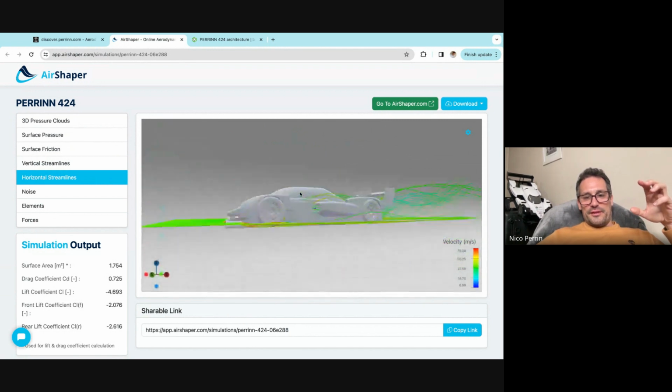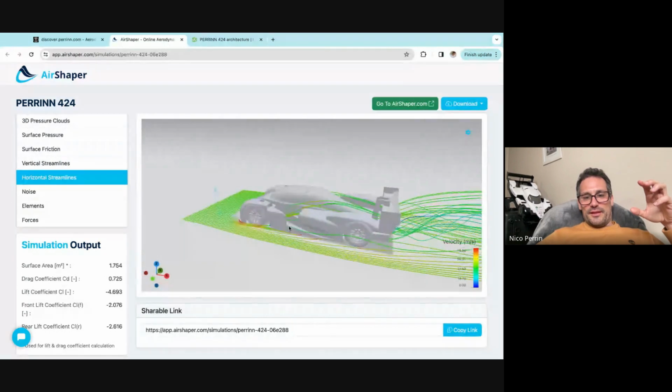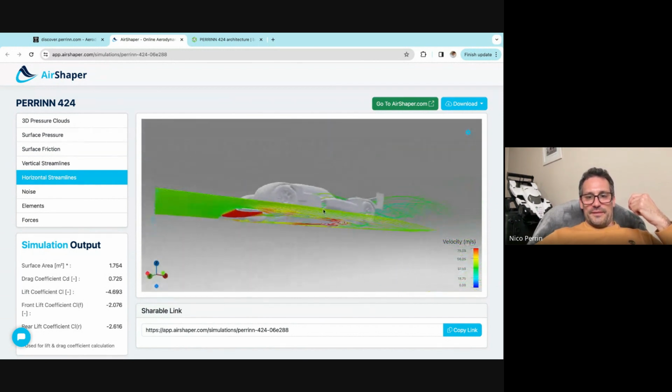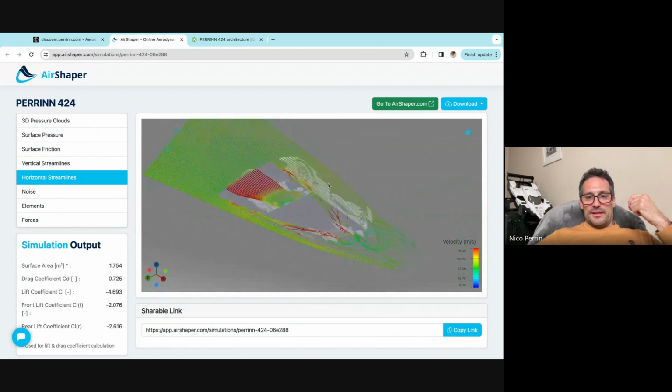It's going over the front wing and is basically extracted on top of the body through these channels here and this volume we have here. That allows us, using the turning vanes on the side, to feed air from the side to the floor. And you see how then that air rotates around the fin in the diffuser area.